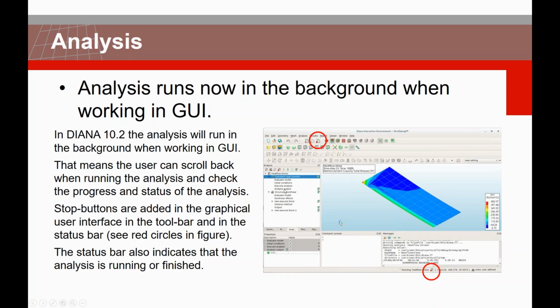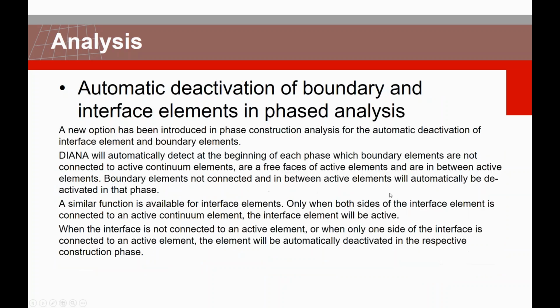remesh the model, because when you do anything about the geometry, loading, or boundary, when you change them, you always have to remesh the model in terms of updating the status of the model information, and then you can redo the analysis. Or, while it's going through the analysis, you can see the results from the previous case, or you can write your report based on the geometry. So there is no limitation. You can go back and do whatever you want from the geometry, meshing, and results inspection.